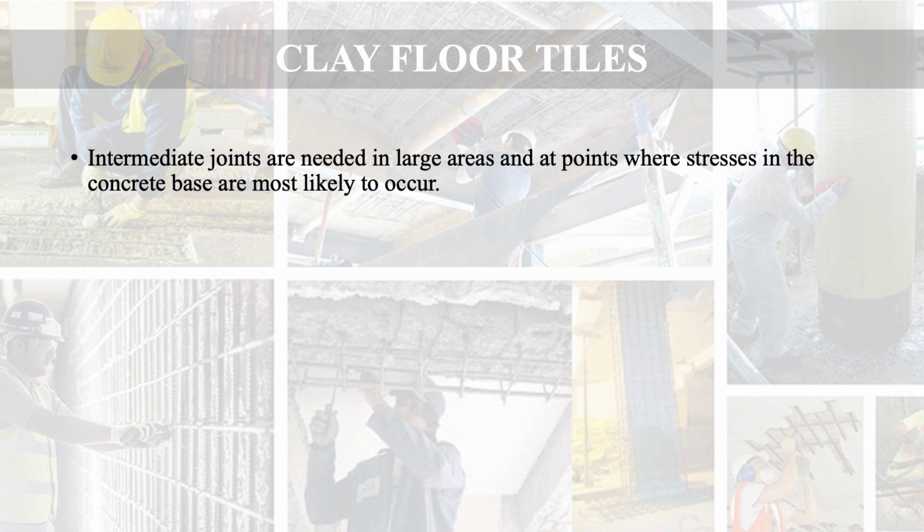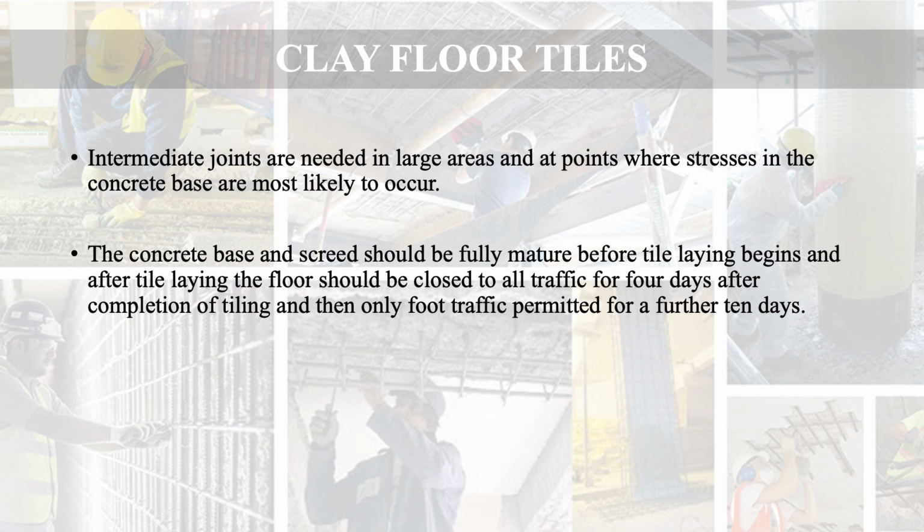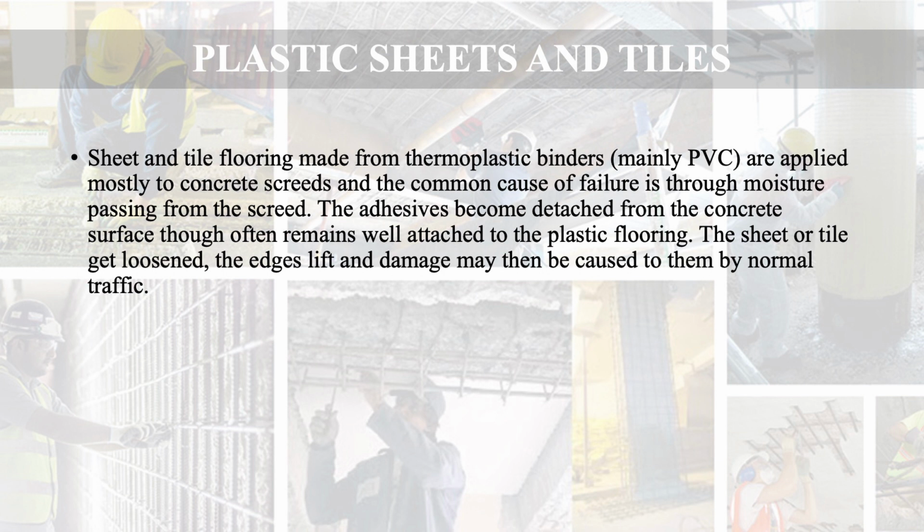Intermediate joints are needed in large areas and at points where stresses in the concrete base are most likely to occur. The concrete base and screed should be fully mature before tile laying begins, and after tile laying, the floor should be closed to all traffic for 4 days after completion of tiling, and then only foot traffic permitted for a further 10 days. Now we move to another type of floor, that is plastic sheets and tiles.